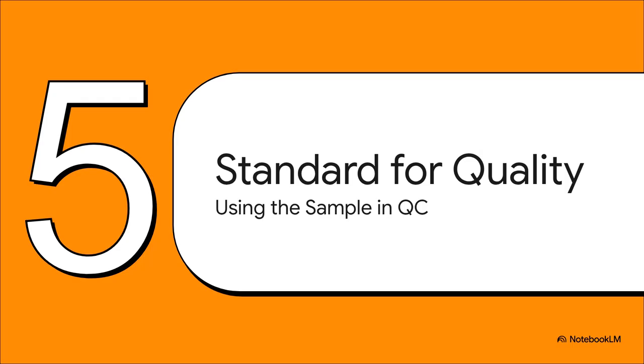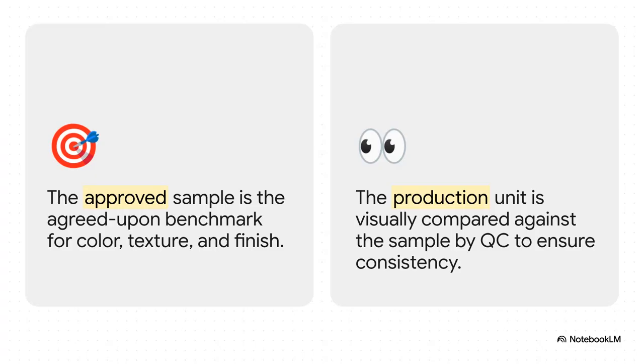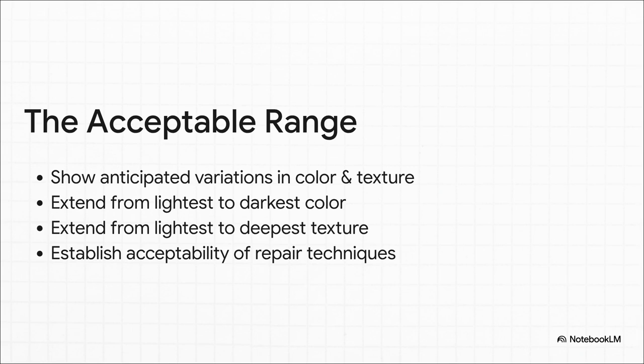But listen, once you get that sign-off, the sample's job is not over, not by a long shot. In fact, it immediately gets a promotion. It goes from being an approval tool to being the number one benchmark for your daily QC inspections. So if you're a QC tech, this right here is your bread and butter. The job is really straightforward. You hold up the production unit and compare it directly against that approved sample. That side-by-side check is, without a doubt, the best way to make sure every single panel leaving that plant is consistent.